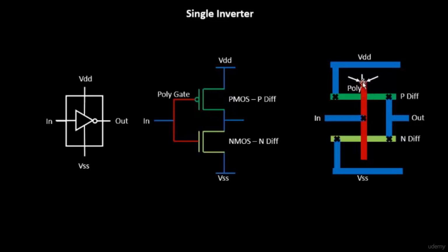So this is what decides at which technology node you are. Okay, and this is the width of the gate. There is something called the W by L ratio. We have always been seeing this W by L in the equations. So this is the width. Width identifies the overlap area of the gate on the P diffusion region. That is what defines your width.